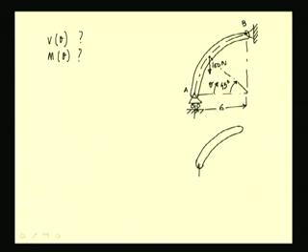So, at A we have a roller support and at B we have a pin support, and we have an externally applied load of 100 newtons. The radius is 6 meters. So, let us write the equations resulting from this free body diagram.